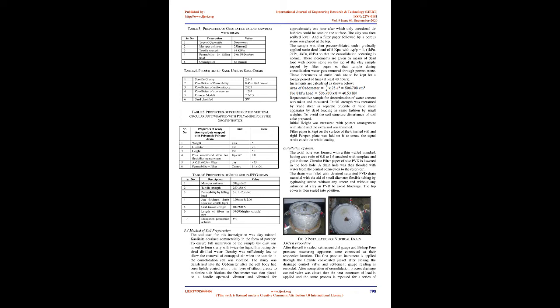It is intended to conduct a series of consolidation tests with radial drainage through a vertical geodrain centrally placed, and measurement of settlement and pore water pressure at three radial distances will be taken so as to prove efficacy against various physical factors, namely type of drain material, shape, aspect ratio, various shapes of drain, and n value, i.e. different diameters of drain related to the influence zone.